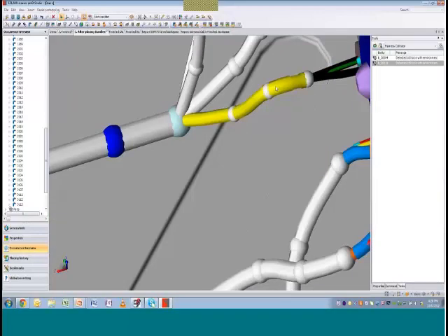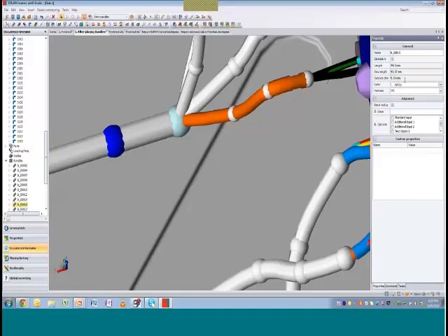You also have here the bend radius. The little red indicator there identifies that there is a bend radius issue. So by clicking on my harness, I can see that my outer diameter is 528. It's calculated in the background the size of these wires going through.